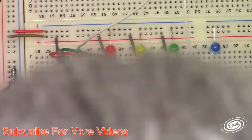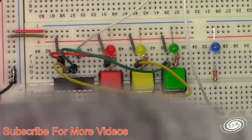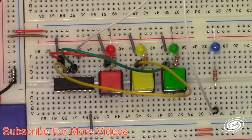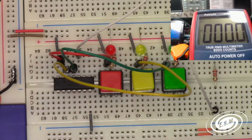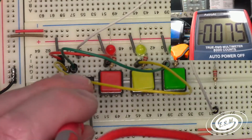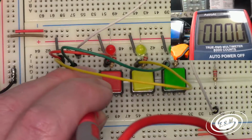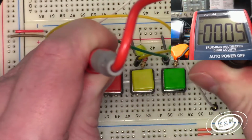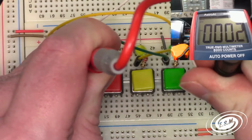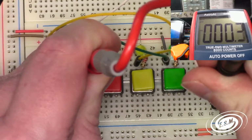So I want to read the signal off of pin 10. I read the voltage. So we're going to read the DC voltage off of pin 10, and I have 0 volts on pin 10.